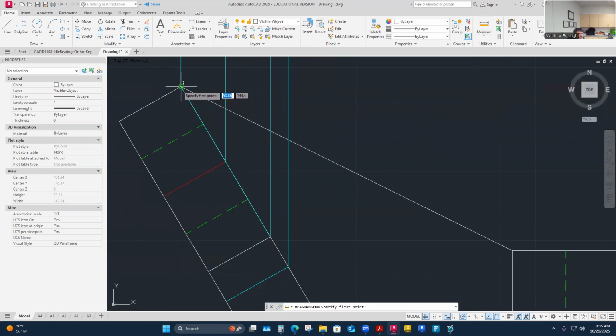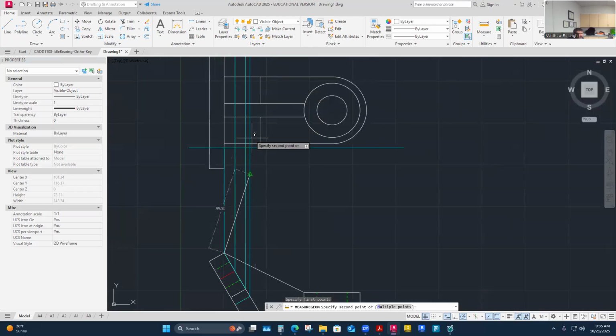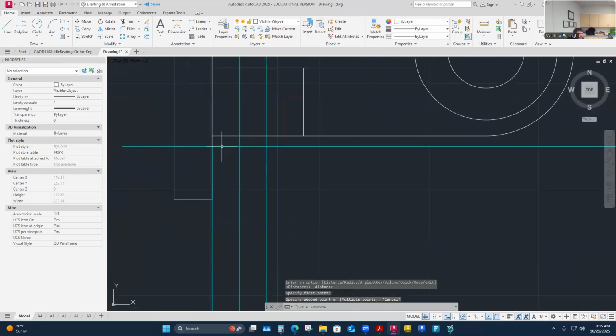And so this distance becomes this far. It's only 25 across here. It measures 50 here, but the distorted image of this ends up being half. It's not always half. It just happens to be the slope that we're at here, at 30 or 120 degrees over, and 50 millimeters ends up producing this projection that is 25 millimeters across. So that's the length from center out here, how long the ellipse would be in this way. And that's what I would consider its minor axis here.